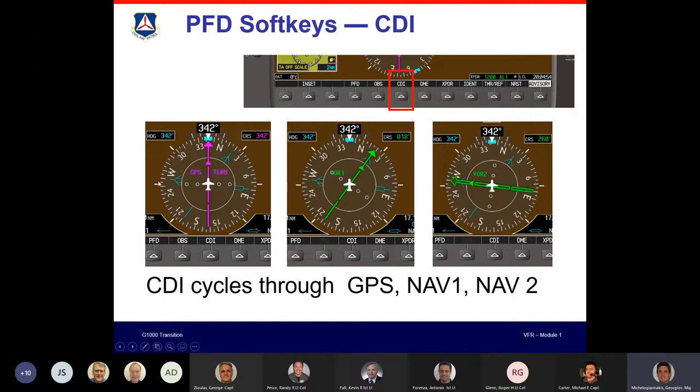And remember, I said that they point towards. So in this case, for example, VOR2, nav2, the heading that you would fly to get to it would be 260. But if you look at the other side of the needle, that tells you the radial that you are from it. So in this case, you're on radial 080.